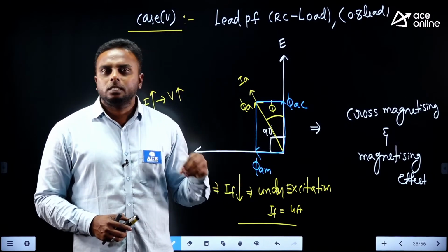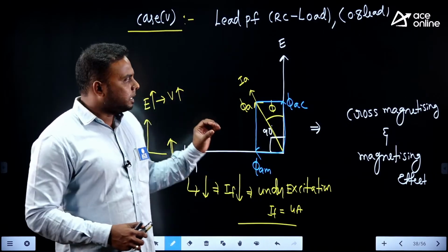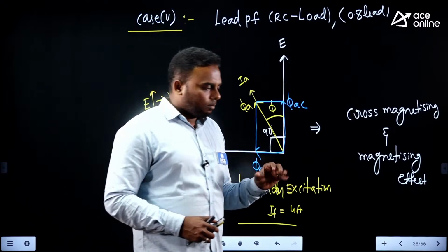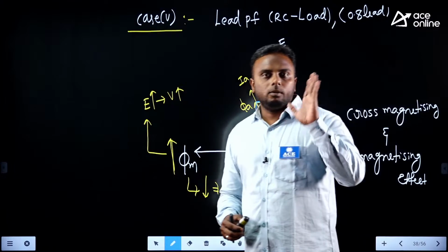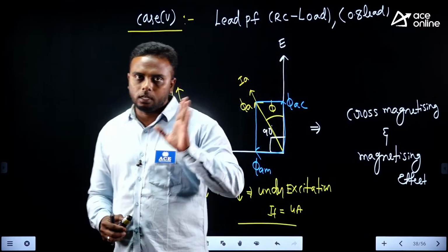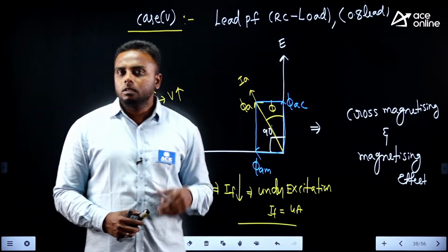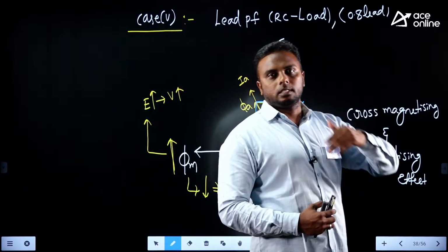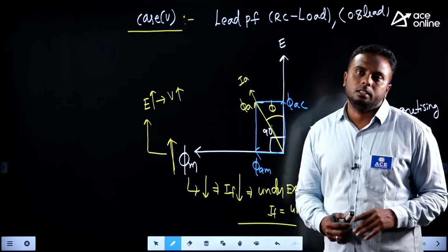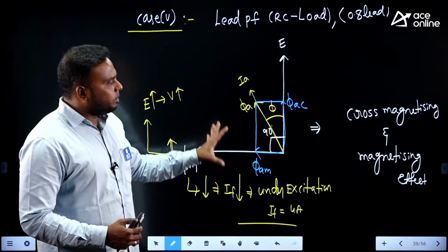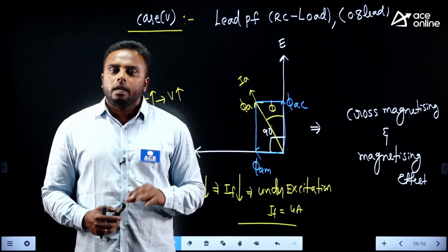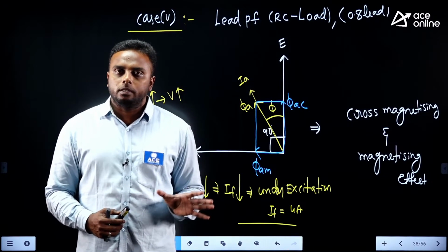That's it. Synchronous motor, same as it is, we have to draw the phasor diagram. But the difference is, in alternator current IA will come outside to the load, but in synchronous motor the same current IA will go inside. Current will become opposite. So to avoid all this problem, remember for alternator perfectly and answer for motor opposite to it.